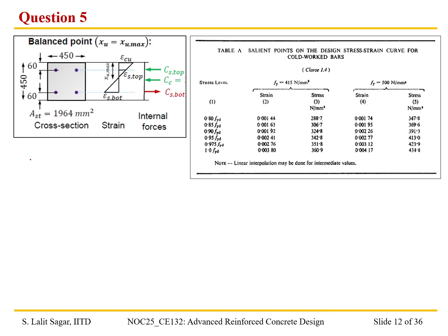We have CC is equal to 0.36 FCK into B into XU, that is 0.36 into 30 into 450, and XU is 177.84, which gives me a value of 864.3 kilonewton.